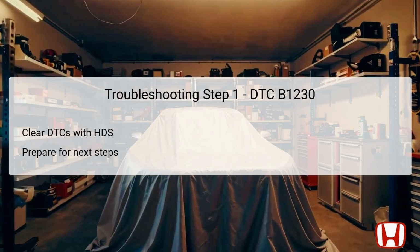reliability. The first step in troubleshooting DTC B1230 involves using the Honda Diagnostic System (HDS) to clear any existing diagnostic trouble codes, DTCs. Clearing the DTCs helps reset the vehicle's computer system and allows technicians to determine if the issue is ongoing or intermittent. After clearing, it's important to switch the ignition to the LOCK (0) position and then back to ON (II). This action prepares the vehicle systems for the next part of the self-diagnostic procedure.